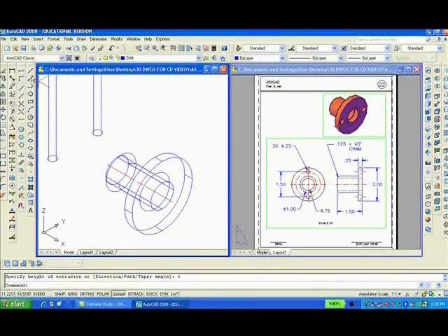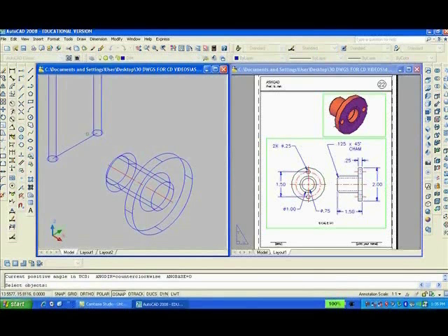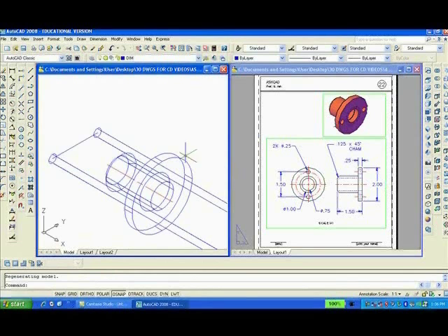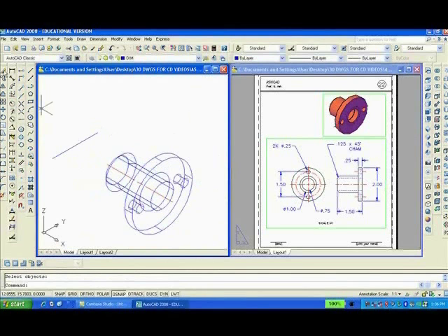I suppose I could also, this is funny, I could draw a line from center there to center there. And I could 3D rotate these two cylinders from, let's say, the midpoint here. Rotate them around the green axis, -90. And then I could subtract from that the two cylinders and erase the unnecessary lines.